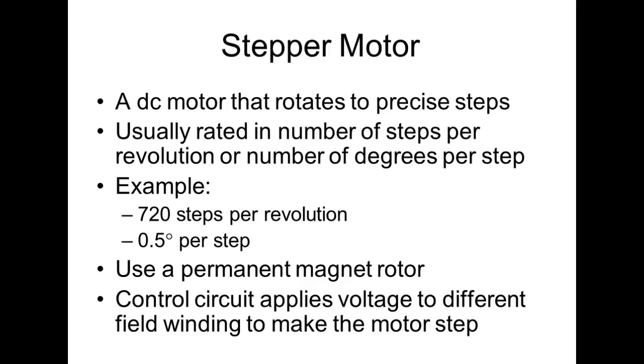With a paper jam in there, it's lost its step. And it might try for a little while, but then again, it'll come back over and find itself. It knows it's stalled, because if it ever hits the end sensors again, there's only one reason it would do that. Why it's stalled. It cripples up your paper and all that other kind of stuff. That don't happen much anymore, thank goodness.